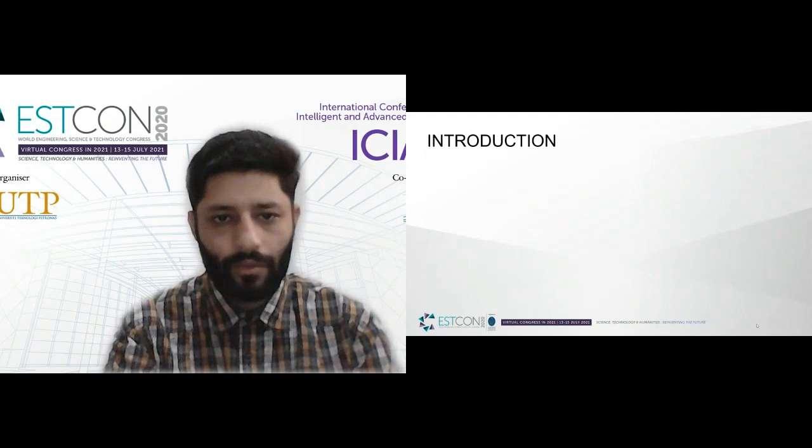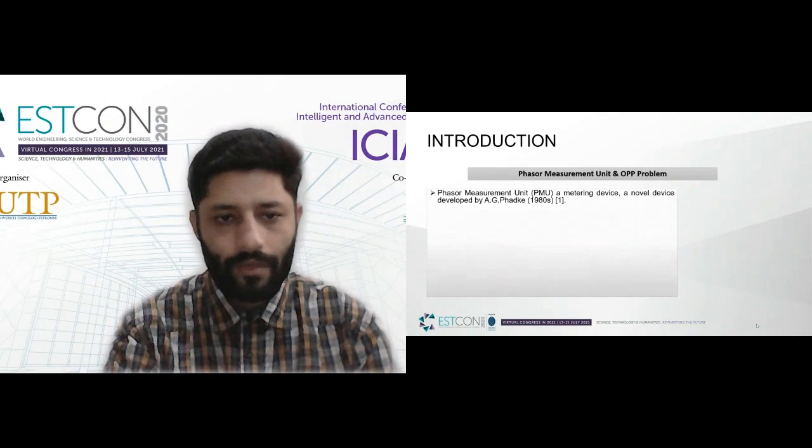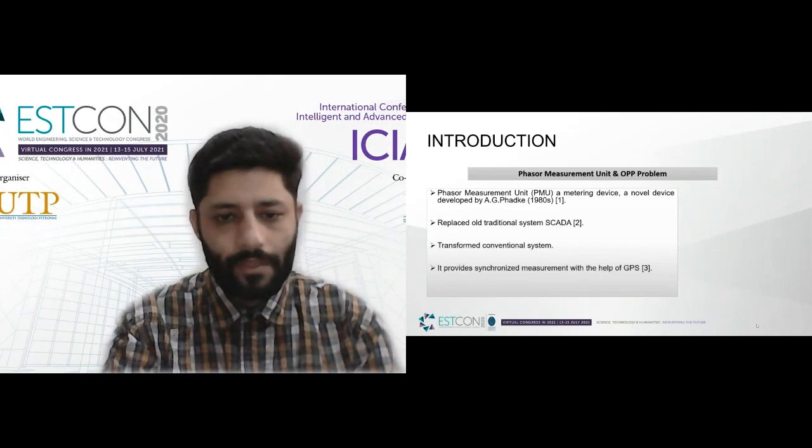Firstly, I will go through the introduction section, in which I will explain what a phasor measurement unit and its OPP problem are. A phasor measurement unit is a modern metering device used to estimate the voltage and current phasors in an electricity grid. This device, made by A.G. Phadke in the 1980s, replaces the old traditional SCADA system and converts it into a smart metering system. It provides synchronized measurement with the help of the global positioning system. This device is installed at bus bars in a grid station.